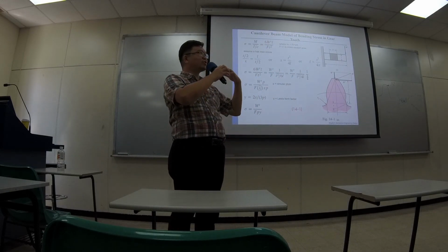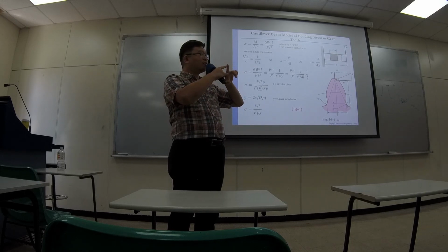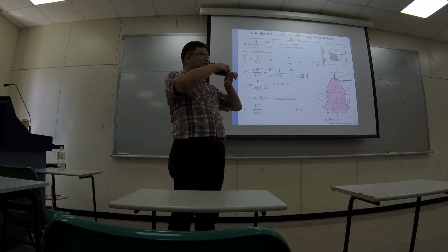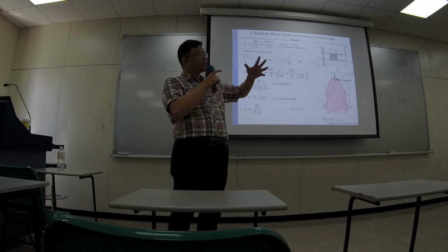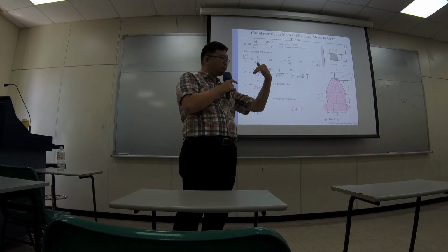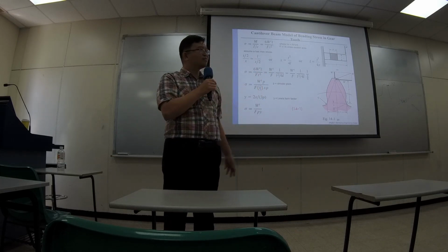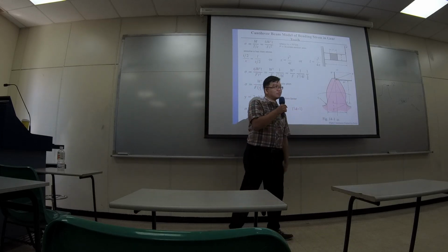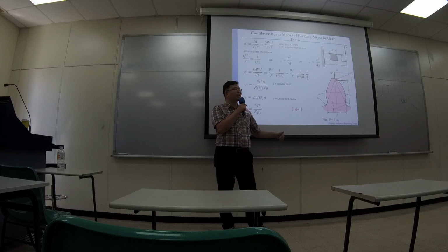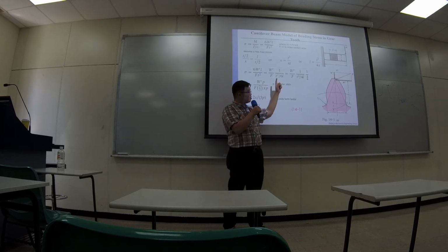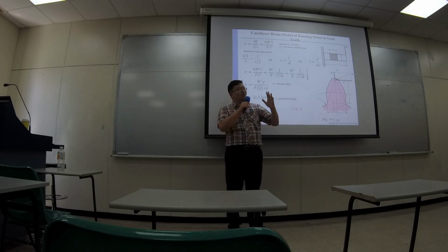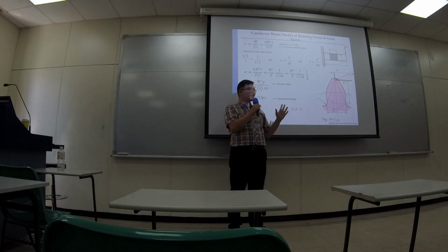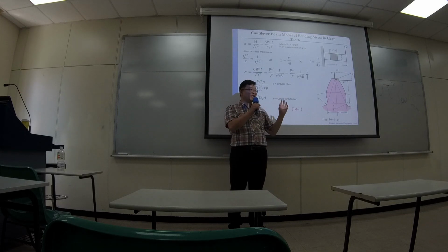Because whenever there's conjugate motion, the force is going to be applied to the teeth at different positions as the teeth revolve. Why do we only do this? Because this is the worst case. If the teeth can survive this case, it can survive all other cases. So for this course, we only care about the worst case, the worst loading case.